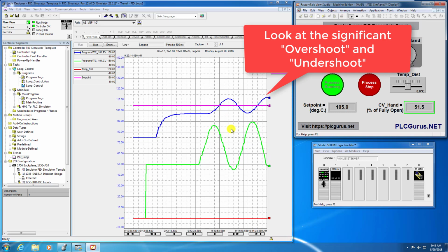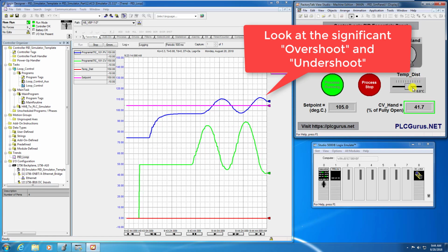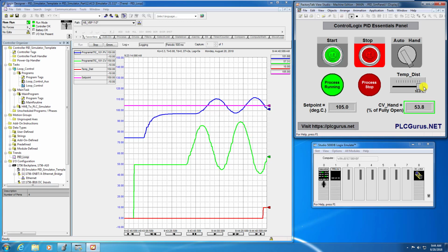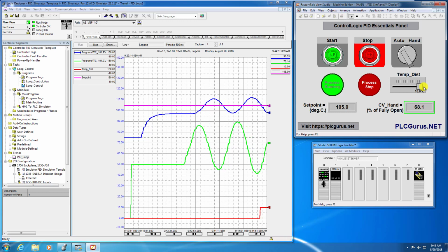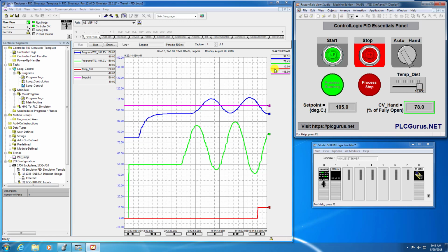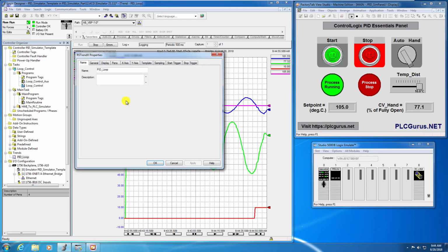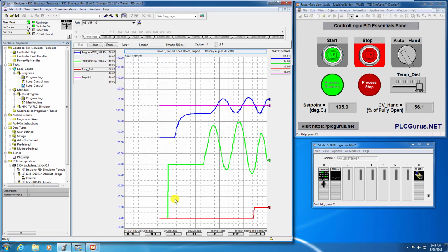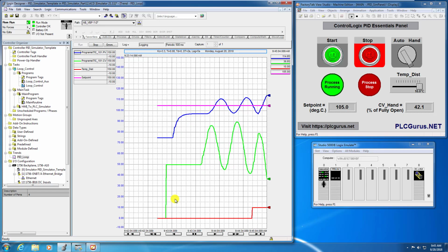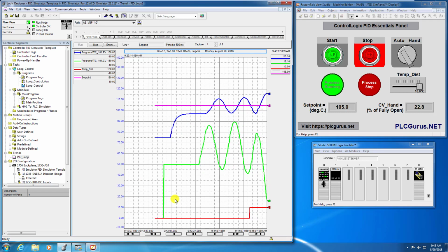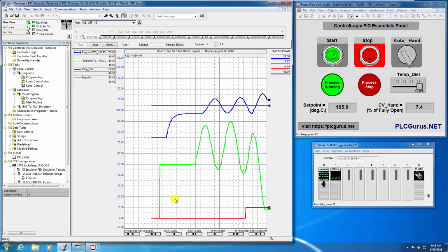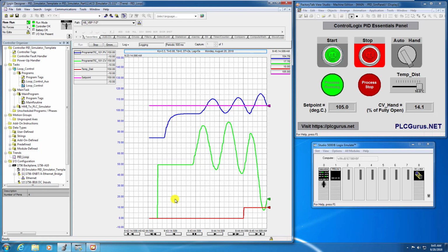And you can see here we are going into instability almost straight away. And if I hit this with a disturbance now, let's go ahead and hit that with a step of 10 degrees C. And let's see what happens. So, I mean, it's already gone. I mean, there's no way this is going to recover. Let's just zoom out a little bit more. I'm going to go to 3 minutes just so we can see more of this trend and watch this function grow. And there we go. So we're seeing the effects of dead time here. When we did have stability with the gains that we had, by adding more dead time, we can see that this thing is just oscillating uncontrollably now.